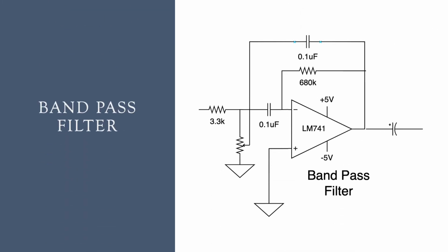In order to isolate the low-frequency parts of the audio signal and send them to a subwoofer, we need to make use of a bandpass filter. Why a bandpass filter, you may ask? If we allowed DC components of the waveform to pass through the filter, the subwoofer would draw power from the filter, which can cause distortion.